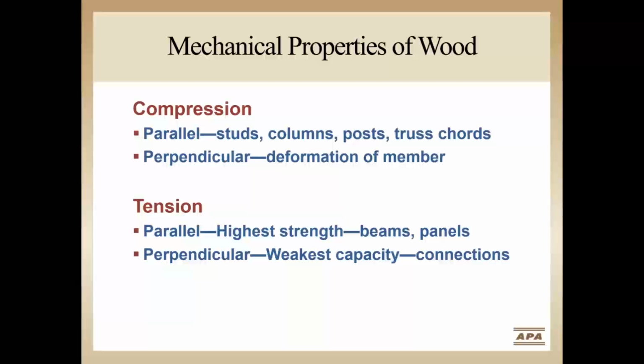In tension, wood performs well with the load applied parallel to the grain, as long as the grain is straight and there are minimum knots and other strength-reducing characteristics. This is the most demanding application for wood performance, and these applications in general require higher quality than compression members. Bending of beams is usually a combination of compression on the top of the beam and tension on the bottom. We'll look at this more closely in the next training module.